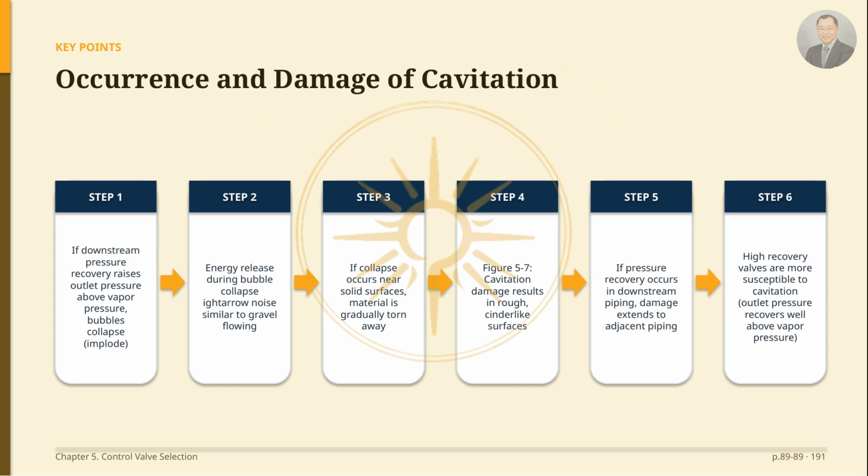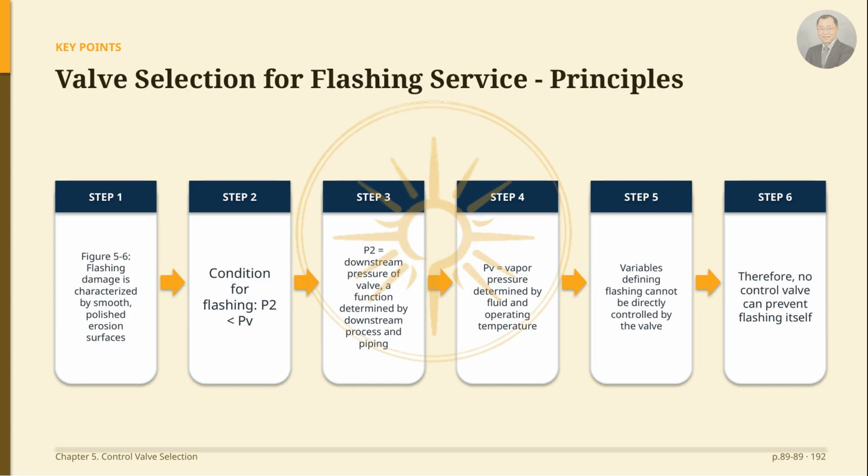Naturally, high recovery valves are more susceptible to cavitation because the outlet pressure is more likely to recover above the vapor pressure. Next, I'll explain the principles of how to select a valve for services where flashing occurs.